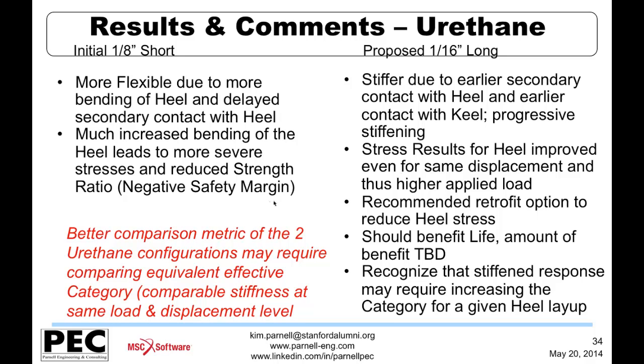But the observations are pretty clear that there's additional flexibility in the shorter component, a lot more bending there that leads to more severe stresses and reduced levels of the strength ratio. And this is really just looking at stress aspects only, not yet delamination or interlaminar types of components.